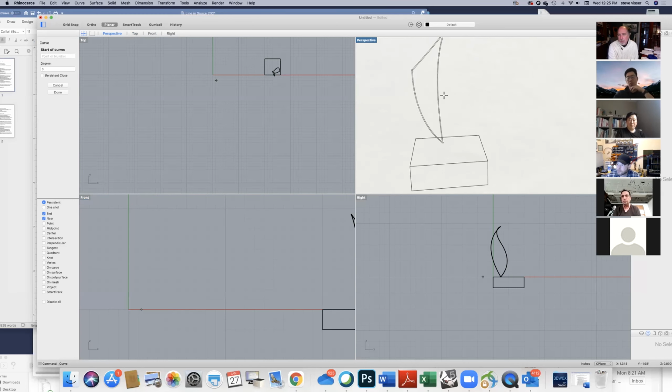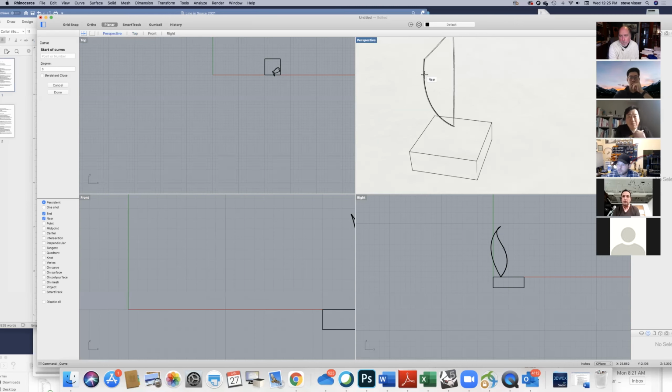But I'm sort of getting between these two, the feeling that they're both going back. So I'm going to go ahead and go with my surface arcing back in that direction. So to do this, I'll make sure planar is turned on. I'll click near at the point I want my arc to start.